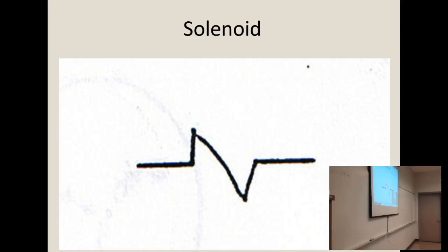There's actually two in here. Can y'all see this in here? Redundant. That way if one gets stuck with some trash in it, we don't keep flowing gas. So we have two redundant. They both have to open to get it to work. And so here we're letting gas flow through. So if I was drawing this symbol, I might put GV in front of that symbol and say, hey, that's my gas valve.